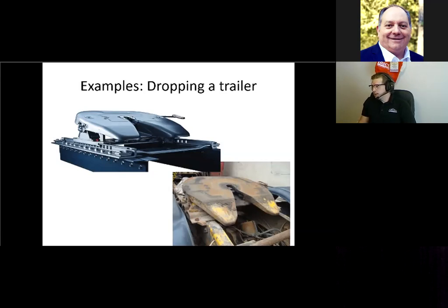It also finds, when investigating this, that this was the first semi rolling off the line on the Monday after industrial vacations in Europe, where people have 5 weeks off. This was the first semi that was done after vacations. So the root cause analysis was that basically we came to the conclusion that in the manufacturing, they'd forgotten to add these remaining bolts. The fifth wheel was still attached by just 4 bolts. Everything looked right. Everything was situated, but the actual support, the strength, was never there.